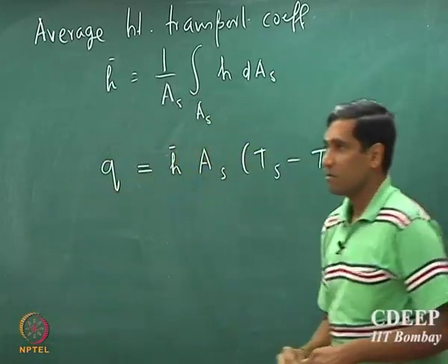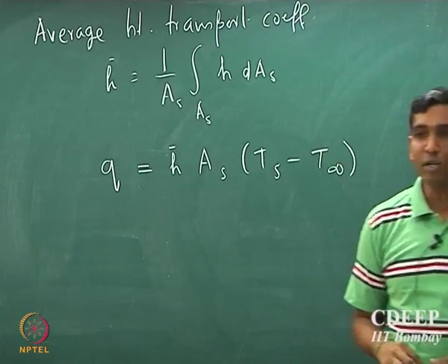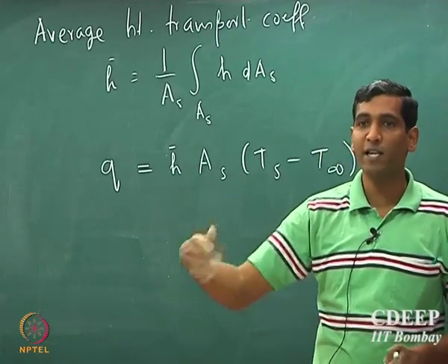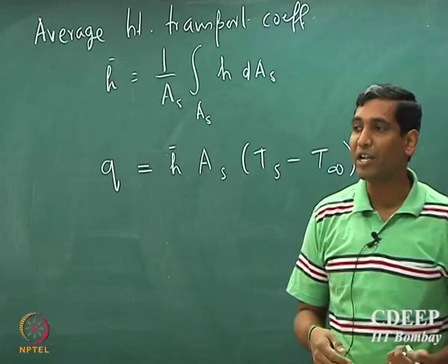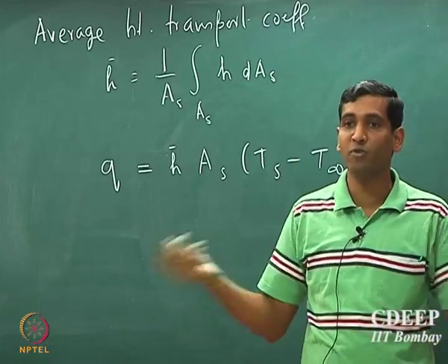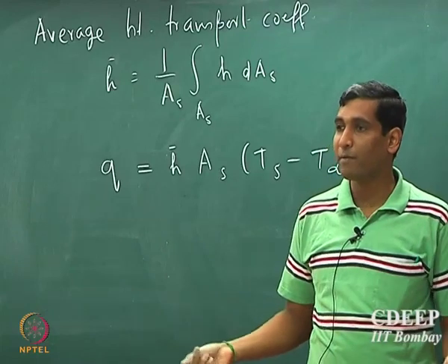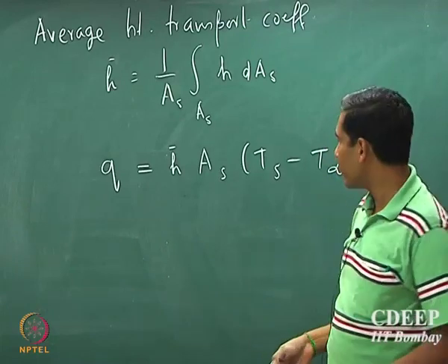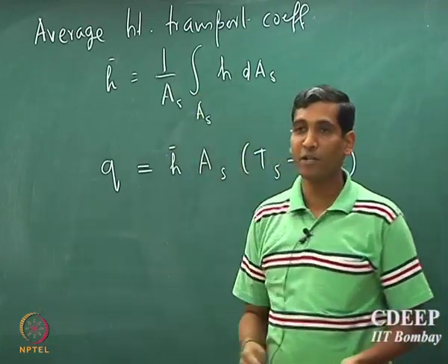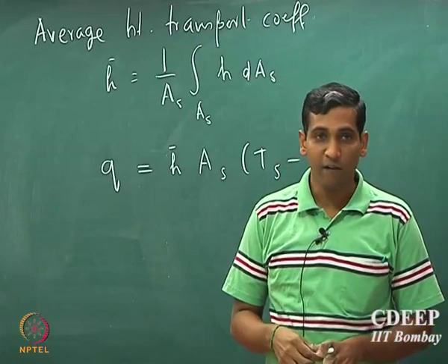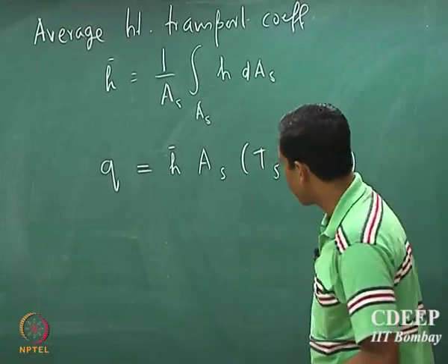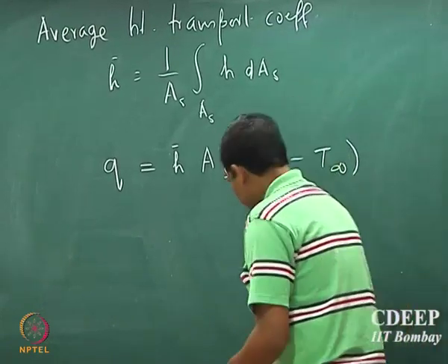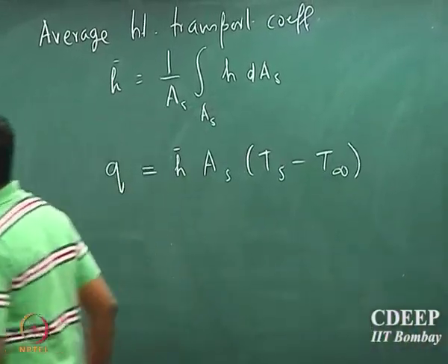Okay. So when we really talk about Newton's law of cooling in the earlier framework, when we discussed conduction, we really meant it is the average heat transport coefficient. We assume that it doesn't change, and so it's the average that we were looking at. So in principle, the heat transport coefficient can be a function of position, it's a function of geometry, it's a function of the flow properties, etc. Okay. Alright, so let's turn back to mass transport.